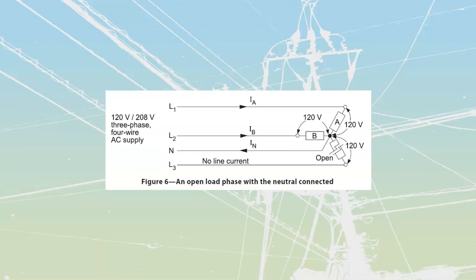Once again, it's going to be that Y type of connection that has got proper value of voltage over top of all 3 loads over here. We're going to be dissipating 2/3 of my watts, but now I'm going to have current along my neutral. I'm going to know that this one is an open load because I see this value of voltage that is placed across it.